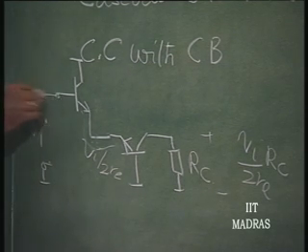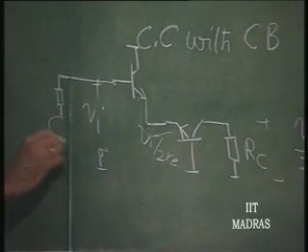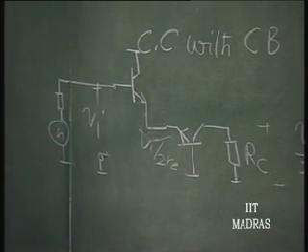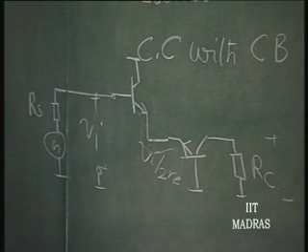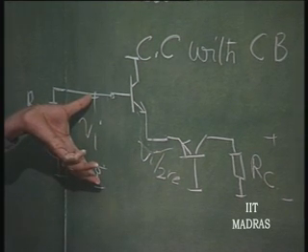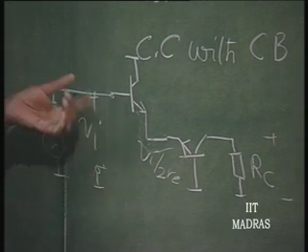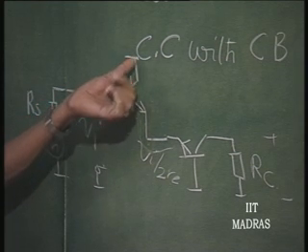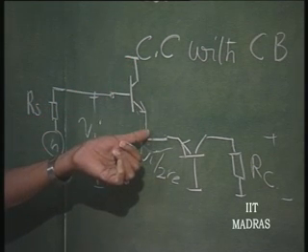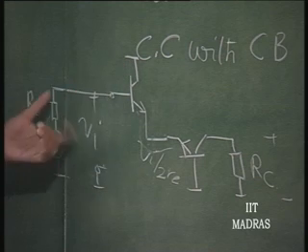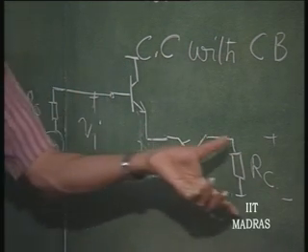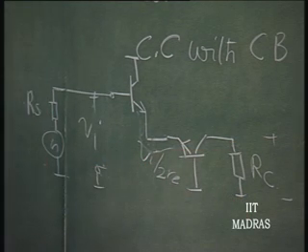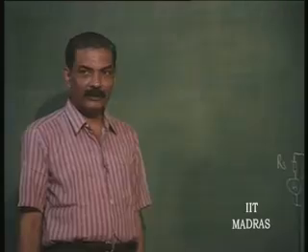At the input here, normally it is driven by means of a voltage source because it is a voltage controlled source. So, source impedance is supposed to be very low. So, capacitance of common collector stage also is very nearly C B dash C because this capacitance does not come into picture much, right. So, the capacitance into Rs which is very low, low time constant. That means this is a wideband structure. Okay. Just like the Cascode, this is a wideband structure.